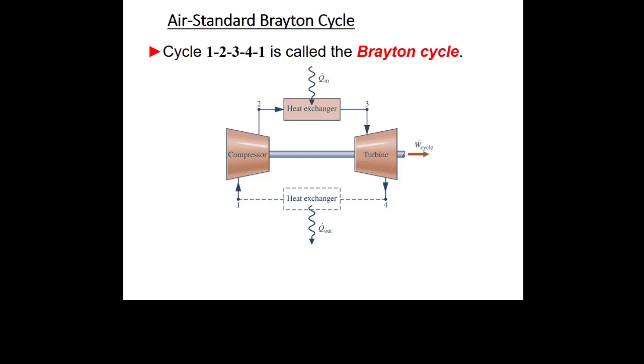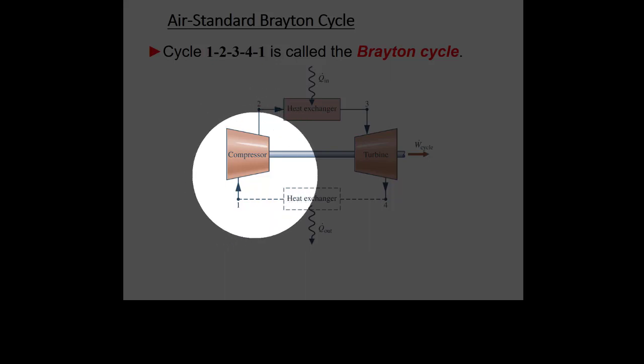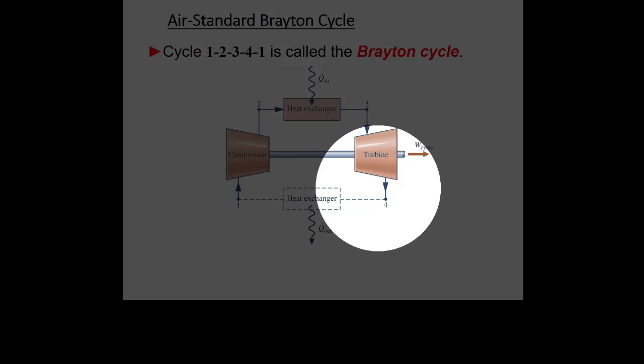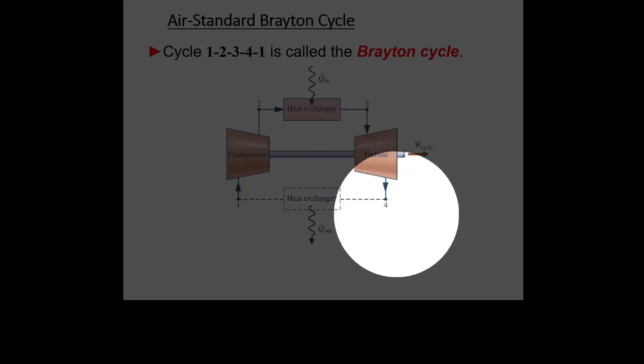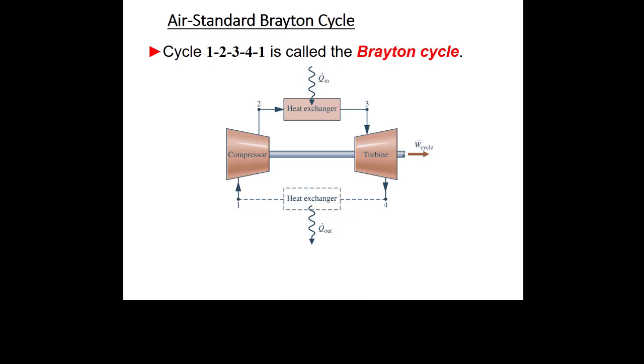Because what we do is we're pulling in fresh air from the environment, right, at a low temperature, and we're exhausting spent air fuel mixture, right? So it's probably got some more carbon dioxide in there. Hopefully it doesn't have things like carbon monoxide or nitrous oxides or anything in there, right? And we dump that out into the environment. And the temperature is higher, right? So you don't want to put your intake right next to your exhaust, right? Because you want to be pulling in fresh air.